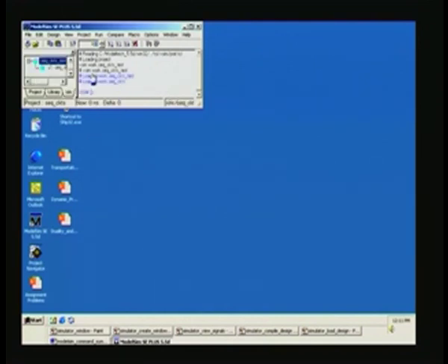So it has successfully loaded. Now you can say do, and the waveform name we have given is sequential circuits, and remember to give that extension .do also, then only it can run. Let us see what happens. It says cannot open macro file.